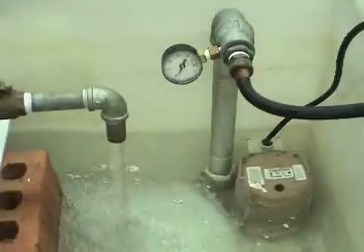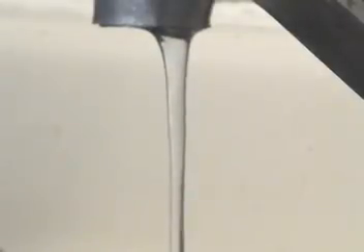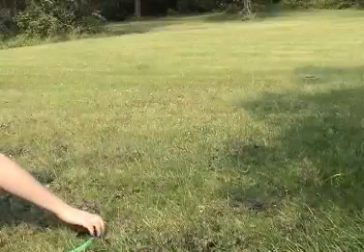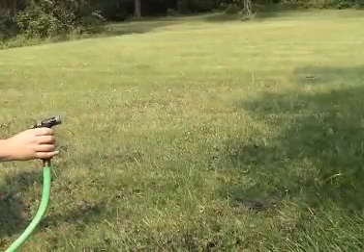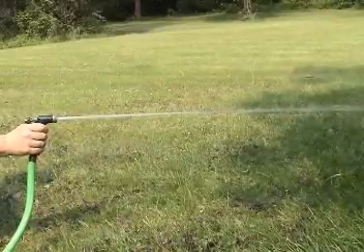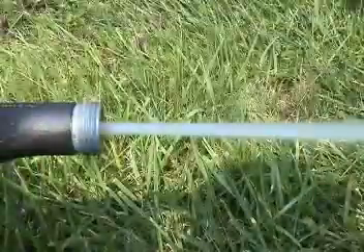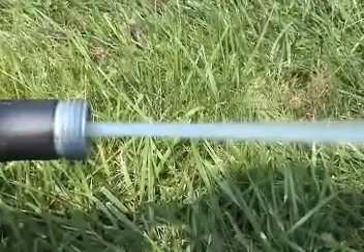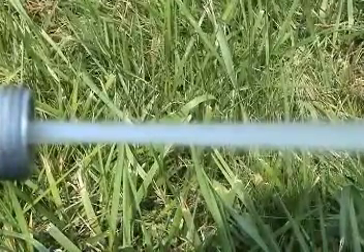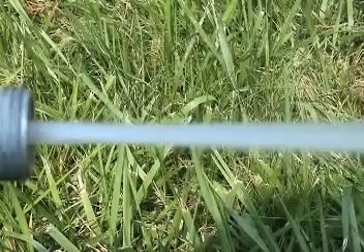Another classification of fluid flows is steady versus unsteady. By carefully adjusting the kitchen faucet, we can produce a stream of water that is not only laminar, but also steady, except for an occasional wiggle. The stream of water from this garden hose is turbulent, as one can tell from both its appearance and its sound. However, the water pressure that drives it, the nozzle diameter, and the speed of the stream are all constant on average if one ignores the turbulent fluctuations. We call this a stationary flow, or a flow that is steady in the mean.